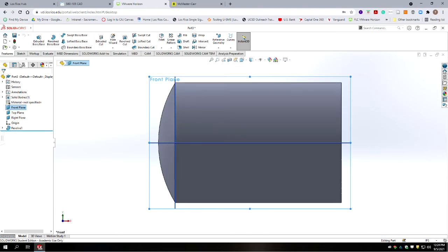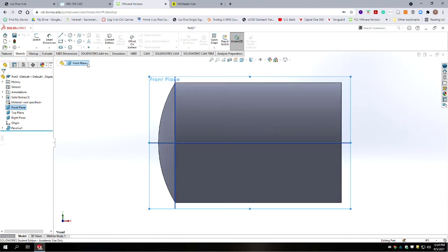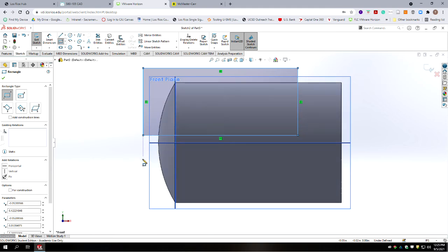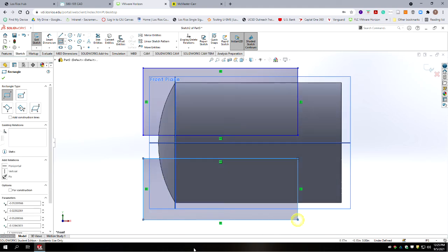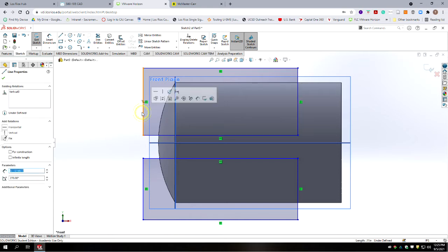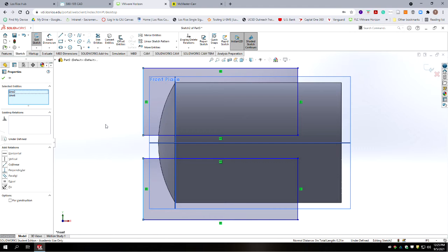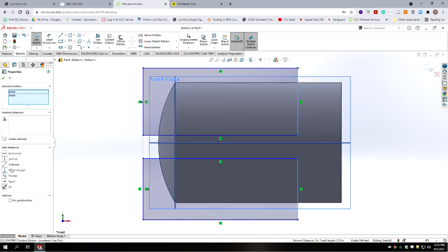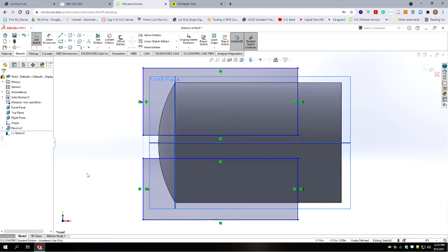Here's the center of our part. I'm going to sketch a rectangle, and I'm going to intentionally try to avoid things that would give me an auto snap. Okay, so I've got two rectangles. They're not defined how far apart they are. I want to make some relationships between the two rectangles. So I want the two lines there to always be collinear. I want the two lines in the back to be collinear. So no matter what dimension they are, they'll be collinear to each other.